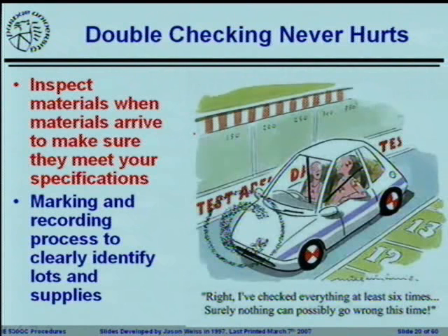We talked about the idea of double checking, here the idea of just sampling. Many times this will help you out considerably because now you have a record of the materials, even if you don't test it. I used to work for a company where we would just pull aggregate samples, and I would say that 80% of them were never even tested and would be dumped back out. But if there was a problem while it was going down, they actually had the materials that were going in through the process.